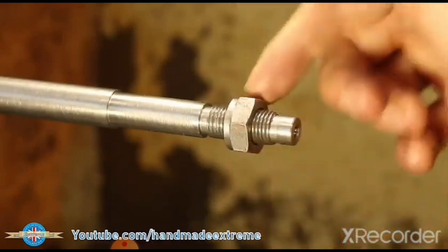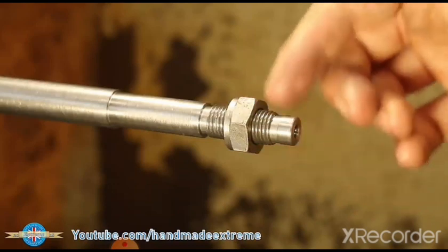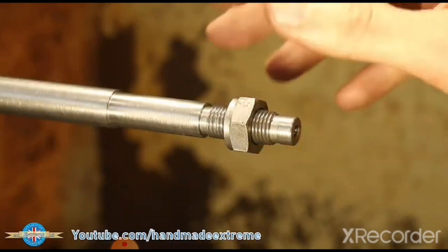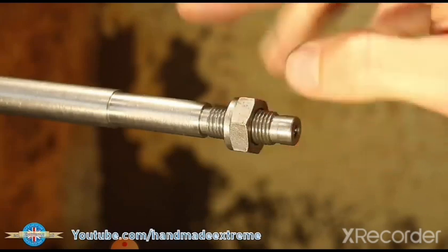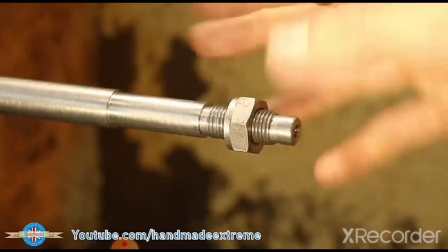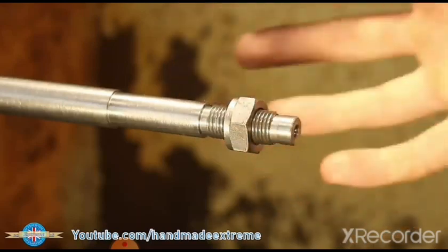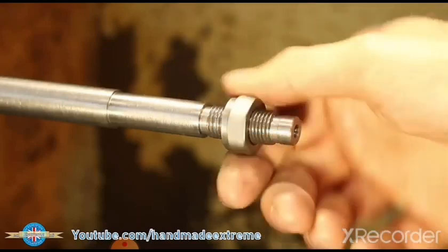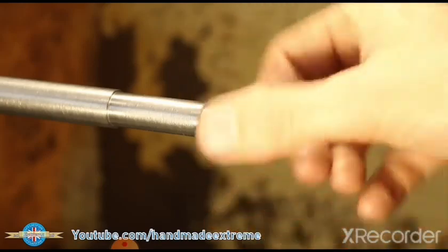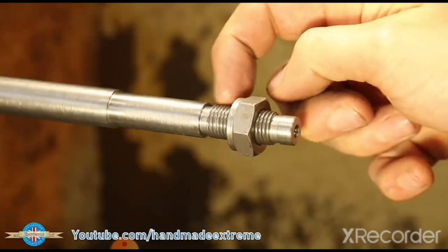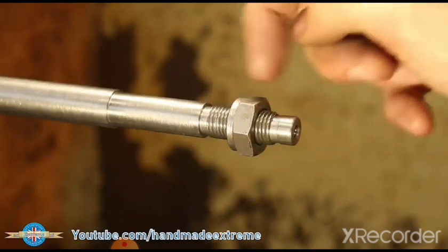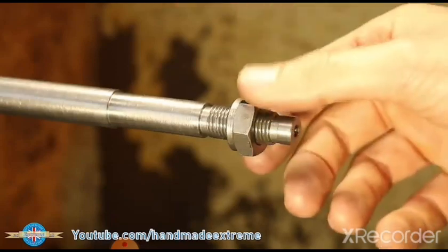Now, if you're just doing small threads like this and you're a hobbyist, I think this is a good way of doing it. If you're doing great big parts, cutting great big threads with big tools, well, I'd use the more advanced method because it's going to reduce the tool load. But small parts, hobby home workshop stuff, I think this is a nice way of doing it. Because like you saw, I made that little mistake, and it's nice and versatile. I could go in, do a little operation with a different tool, come back, pick up my thread where I left off, and